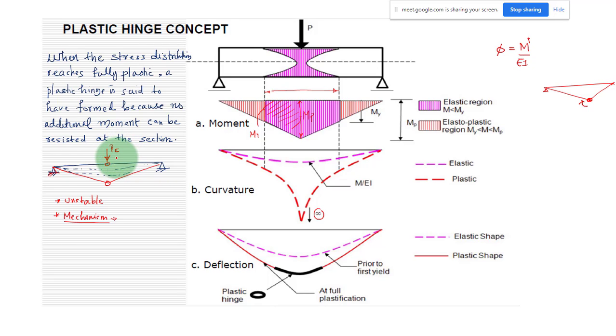Okay, something like in working stress method design, we usually take a factor of safety for the material strength. We usually take a factor of safety for the yield strength. So if you take a factor of safety of 2, that means for the design you will be taking only sigma y by 2, only that strength will be considered. Okay, that is what we will do in the working stress method.